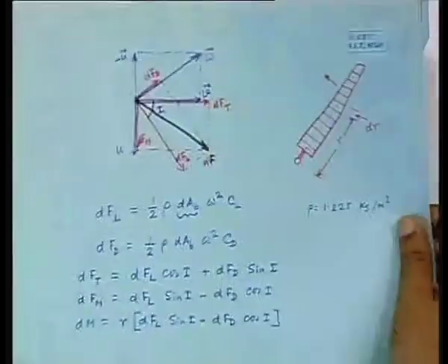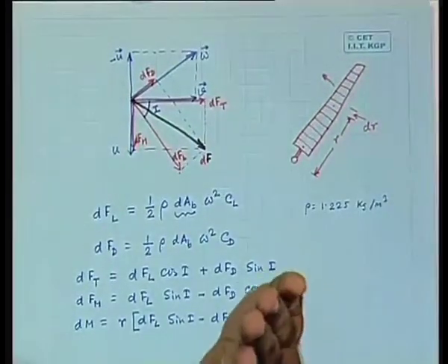Now that doesn't happen automatically. We need to do something in order to make that happen. And the lever in our hand is often, in the case of large wind turbines, the pitch angle. So we vary the pitch angle as the wind speed changes. Why would you need to vary the pitch angle? Because all the time we like to be aligned with the relative wind,